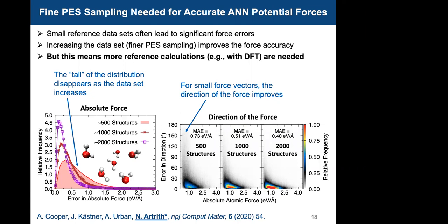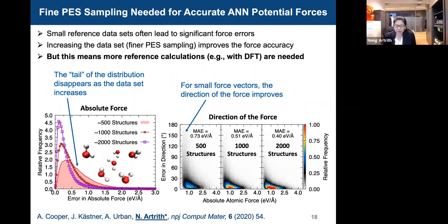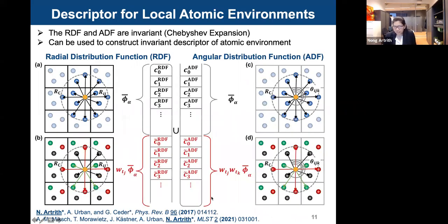Then the second question is, how do you choose the cutoff radius for fitting amorphous structures? This is a very good question. The cutoff radius really depends on your materials. We use 6 to 8 angstroms to capture the long-range amorphous structures, because it can be a large system.